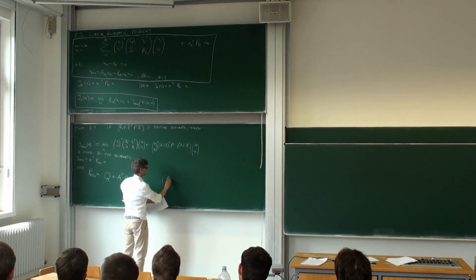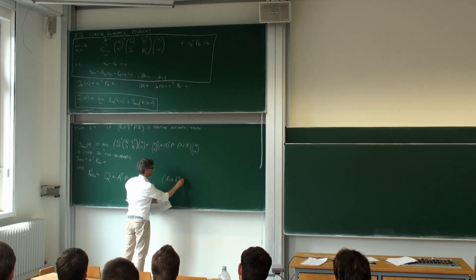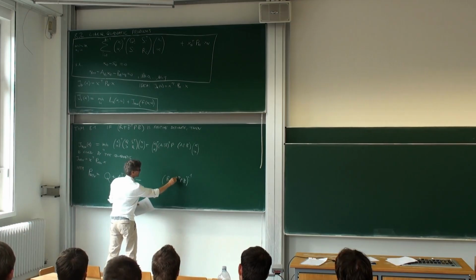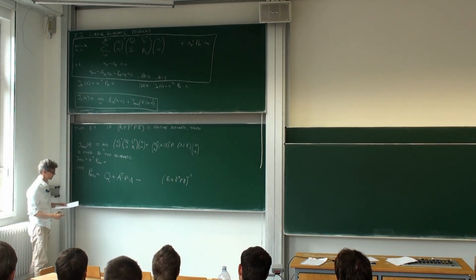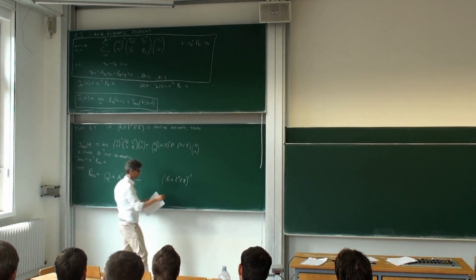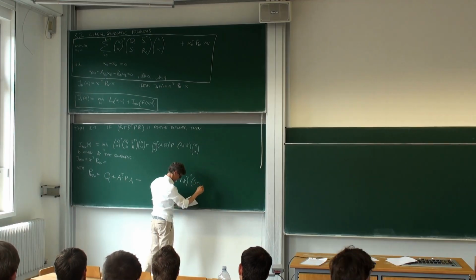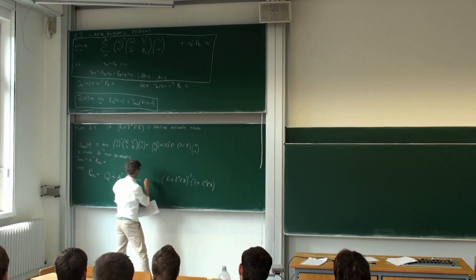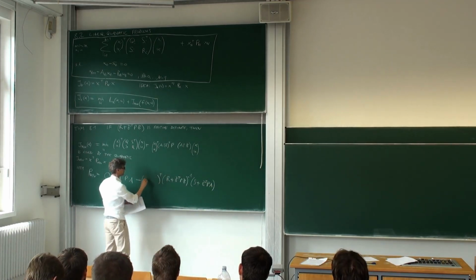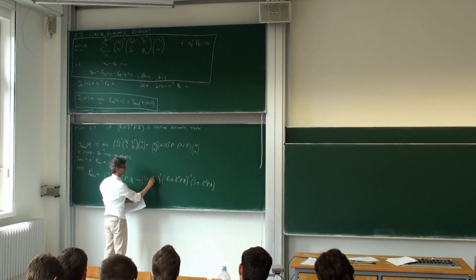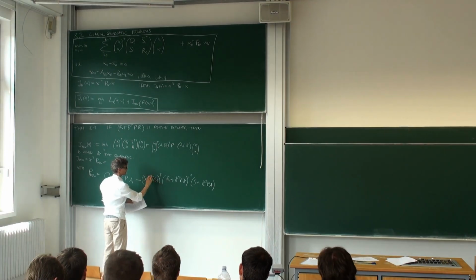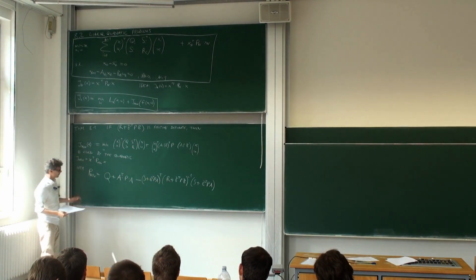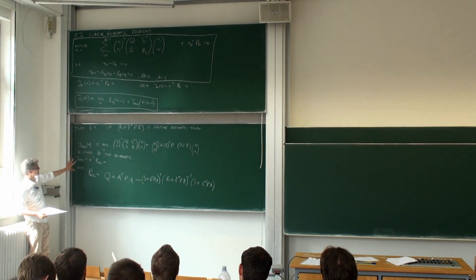And there is in the middle the (R + B^T P B)^(-1). That's why I need this thing to be positive definite, so it's also invertible. And then there's a term on the right, which is S + B^T P A. And here the same term, transposed: S + B^T P A. So it's a complicated expression. We will derive it soon, but this is the main result.